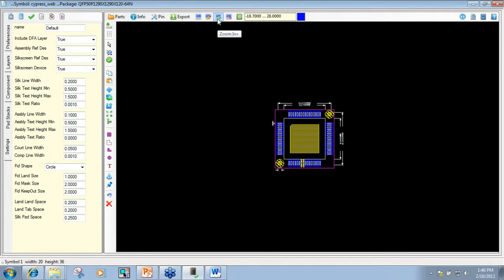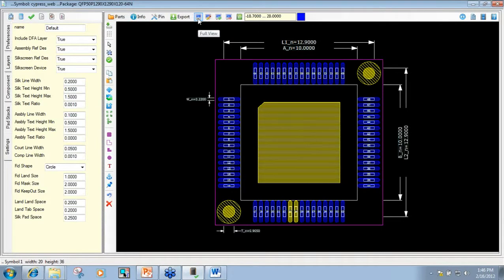If you recall, I deleted 2 pins because I wanted to show you another function. So these 2 pins right here were removed from the data sheet and from the main spreadsheet, so they're highlighted. These other pins weren't part of a logical pin connection on the logic symbol either. They're thermal pad, which could be defined when you export this as just a shape, or it could be a pad stack, but you may or may not want it to be an electrical element. You have that choice when you export. And then the fiducials, obviously, weren't in the spreadsheet as well. So that's just the kind of checking that you can do.